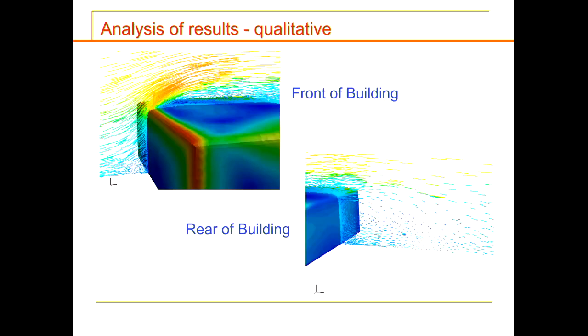Why? Because the flow separates away from the building at high flows. So you have your recirculation region at low velocity, and you can see that the blue color here indicates low velocity as well. So the pictures themselves describe all the physics that you require. And this flow will reattach itself to the main flow somewhere behind the rear of the building.